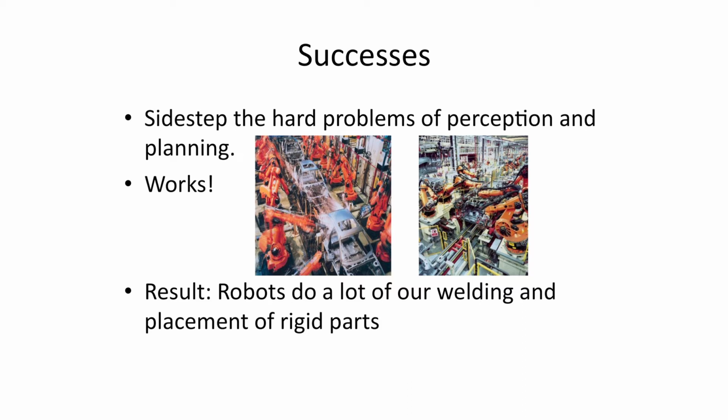So, the paradigm robotic application has been welding. And so, the whole structure of the robotic industry is kind of around this thing. These are blind and dumb, so the whole line of cars, 100 yards or 100 meters of them, is aligned with sub-millimeter accuracy, so these welding robots can weld. And that takes a lot of planning and organization and orchestration.